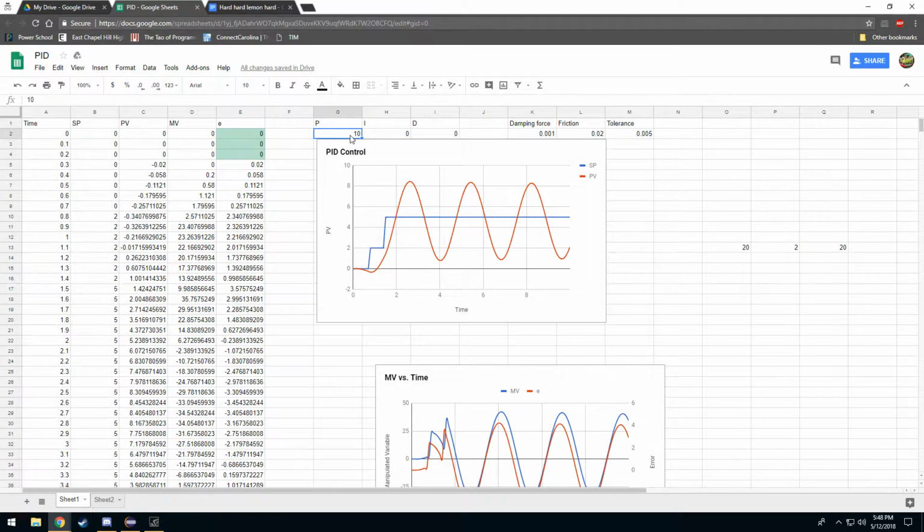So right now this is demonstrating just proportional control. Proportional control is this idea of, okay, how far away are you from your desired point? Let's say you're at 0 feet, but the desired point is 5 feet. So it will apply a force proportional to the error. In this case, my P term is 10, so it'll be 10 times the error. So here at zero, it will go up 10 times as fast until it overshoots. When it overshoots, the algorithm will notice that, hey, I'm 5 feet above now, so my error is negative. So now that negative error is multiplied by your proportional term, and you'll go back down, and you'll oscillate along the point that you want to be.